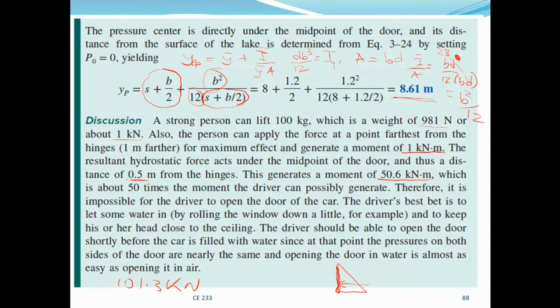Okay, so the best thing is maybe for the driver to open the window so that water can get into the car. By that, the hydrostatic pressure force will reduce from outside, and from inside it will increase, and then before the water level reaches up and fills the car cabin, he can now open the door because there will be hydrostatic pressure acting from inside as well, which will counterbalance the one acting from outside. So it will be much easier to open that way than to attempt to open when you have only